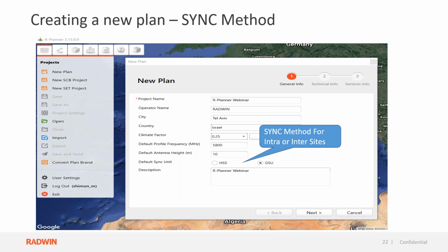And usually, when we have a point-to-multipoint deployment, we are going to enable the integrated GPS for each base station. So it becomes easier. We need just to enable the GPS, and we are all synchronized to one source of clock, the satellite. When it is satellite clock, first it's an accurate clock, and it is the clock that exists. It's easy. When we have one source of clock, all the base stations are synchronized to the GPS clock, and we are synchronized.